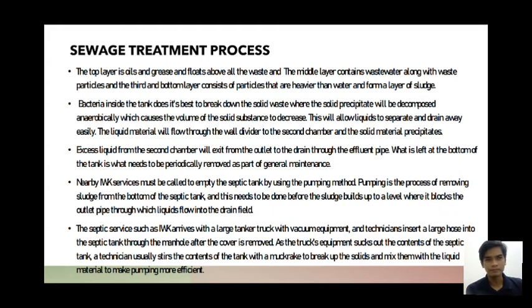The septic service such as IWK arrives with a large tank truck with vacuum equipment, and technicians insert a large hose into the septic tank through the manhole after the cover is removed. As the truck's equipment sucks out the contents of the septic tank, a technician usually stirs the contents of the tank with a muck rake to break up the solids and mix them with the liquid material to make pumping more efficient.